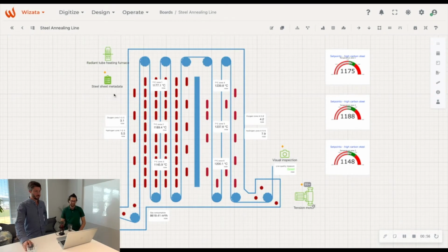Here we have a steel annealing process. This is only the part where you have the actual annealing, because the steel annealing line, of course, is longer than that. You have everything before to uncoil, solder coils together, reheat, and bring the steel back to a condition where it can be annealed. And after the annealing itself, you have several treatments still to be done. You have a slow cooling, then a fast cooling of the steel to give it the proper properties and ductility. And after that you can also have some additional treatments, and again coiling and packaging.